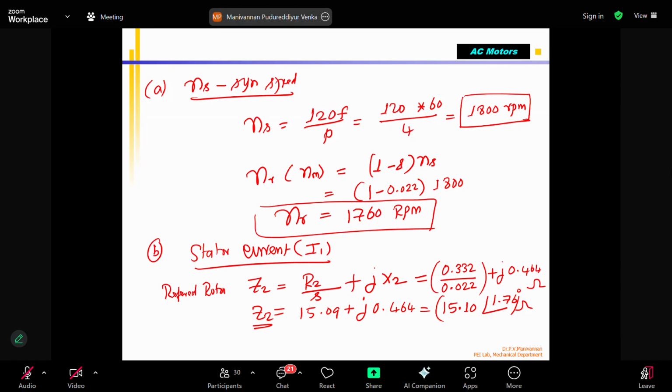The current supplied from the stator induces a magnetic field that is cut by the rotor. A voltage is induced, and since the rotor coils are short circuited, current flows automatically. That is the rotor current, I2, the part of the current going into the rotor. We already saw that, so I am not going to draw it again, as we don't have time.